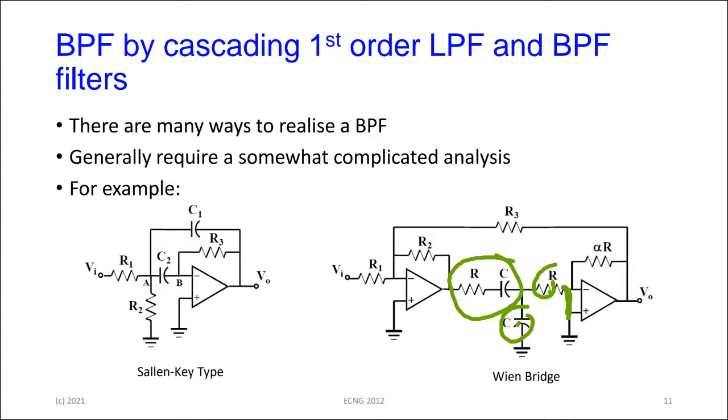So if you put that now into this filter circuit, as the input comes in and passes through, the Wien bridge network will only resonate or respond to whatever frequency is determined by R and C. And the rest of the components around there are really to stabilize that behavior, compensate for any losses, and send the filtered frequency on. The bandpass has to do with exactly what the Wien bridge is set up to do.